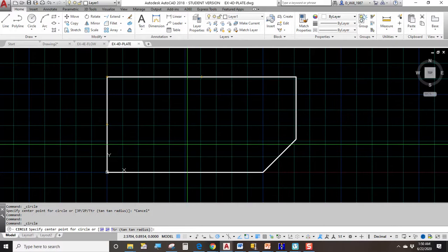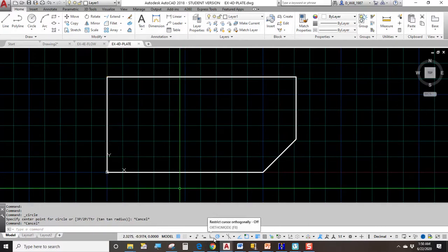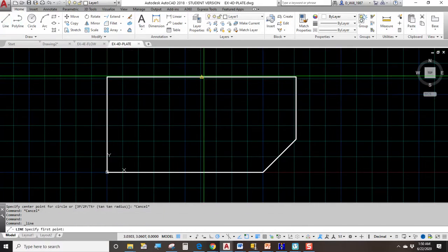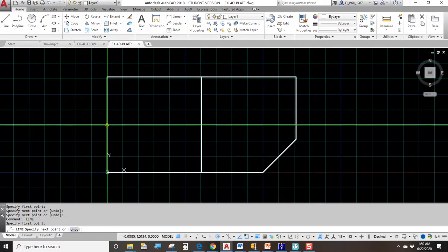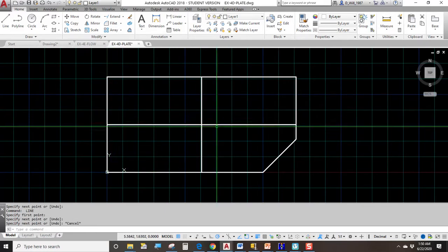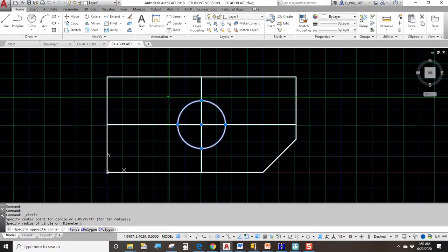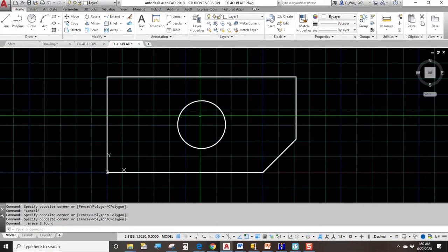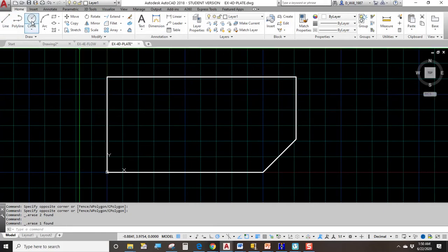So now this would be tricky to do if we didn't have this tool, Object Snap Tracking. What you might be tempted to do is something like this. Draw a line from the midpoint there, draw a line from the midpoint there, and then find the intersection, and then draw a circle at the intersection. Okay, but then you have to go back when you're done and delete those lines you drew. Okay, so there's nothing wrong with drawing lines, it's an extra step, right?